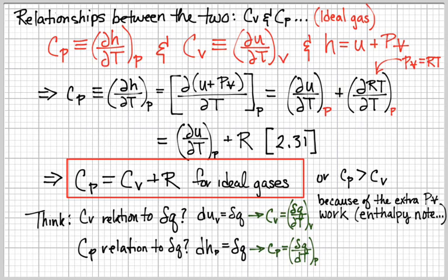Similarly, if I then opened off the lid and allowed that liquid or that gas to expand and contract, but I still input the heat exchanger for Q and had a thermometer for T, I could then measure the heat capacity at constant pressure. And people do this experimentally. So I have a constant volume calorimeter and a constant pressure calorimeter that I could be measuring these values for. And that's going to generate those curves, those functions that then are fit with these empirical polynomial fits with A, B, C, D, E coefficients.